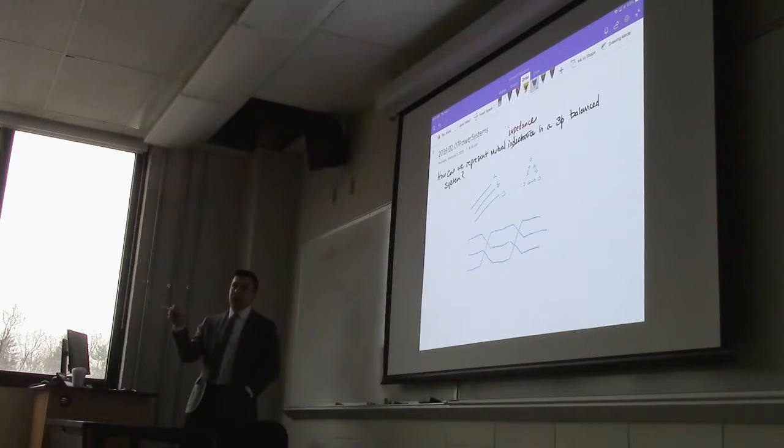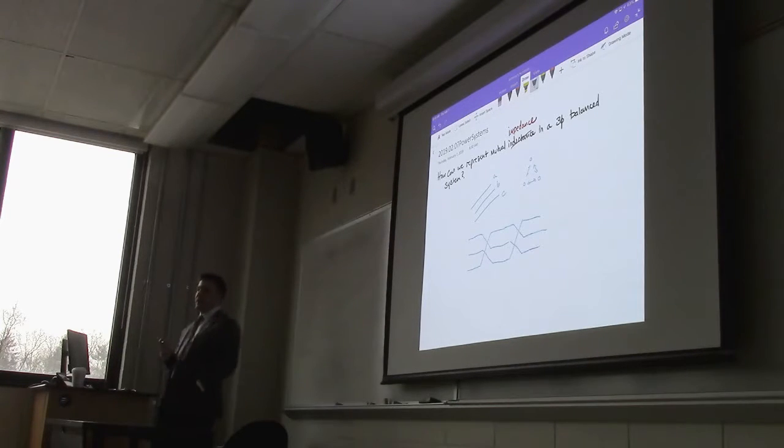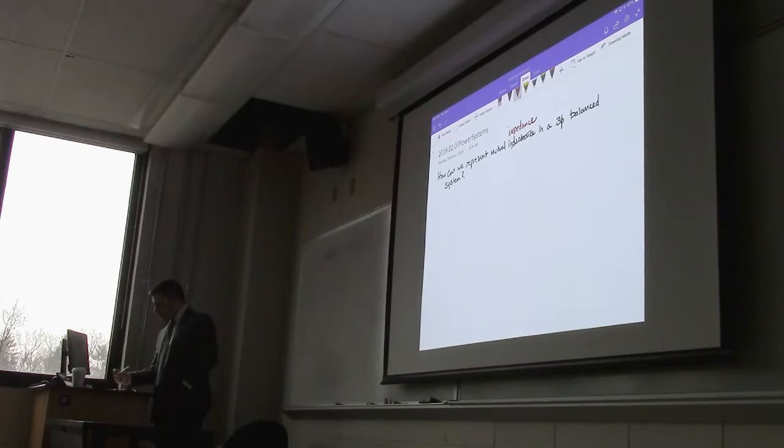By transposing the lines and switching their position over a distance, the average mutual inductance they experience should be equal. So that's another way that we can account for that. I'm not going to spend too much time drawing those nicely. I'm just going to put here, we assume that transposition is used.